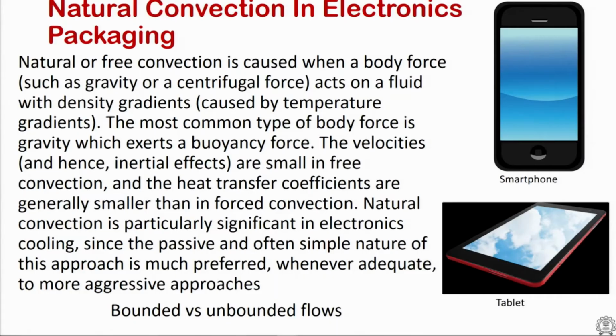Once the skin temperature exceeds that 41 or 45, which becomes ergonomically uneasy to hold, then the processors are typically slowed down, and these phones do not carry any fans. Phones or even tablets for that matter. Some tablets, the so-called tablets that can be converted into laptops, do carry fans with them, but in most of the tablet and smartphone markets, there is no fan in them.